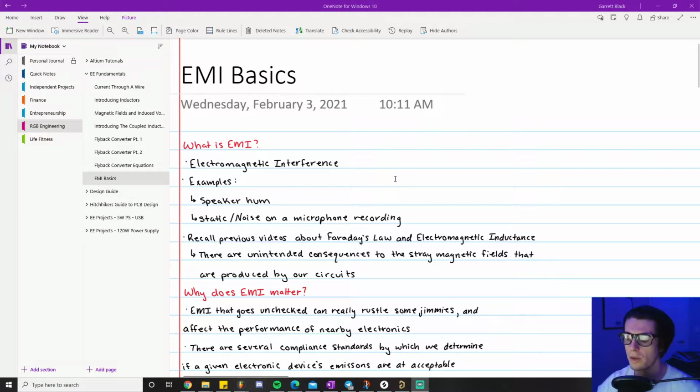So the underlying physical phenomena that create EMI, we've actually already covered before in a previous EE Fundamentals video. So I have a note here, recall previous videos about Faraday's law and electromagnetic inductance. Basically, EMI is an unintended consequence of Faraday's law. It's unwanted electromagnetic inductance.